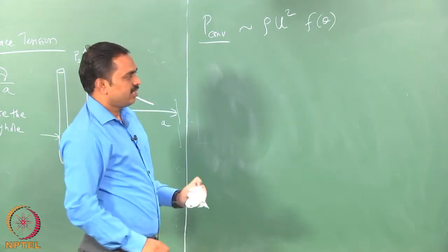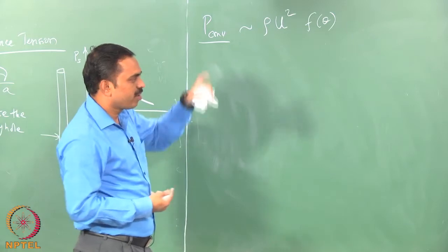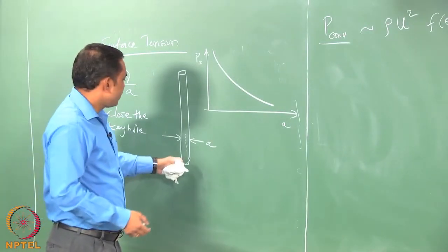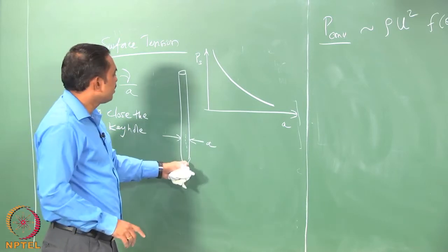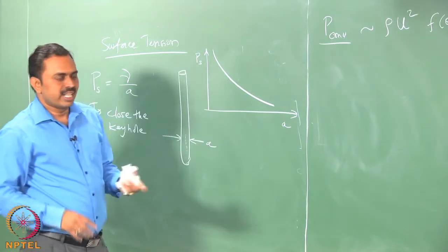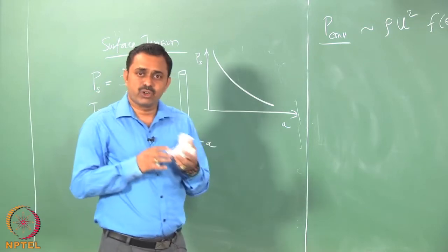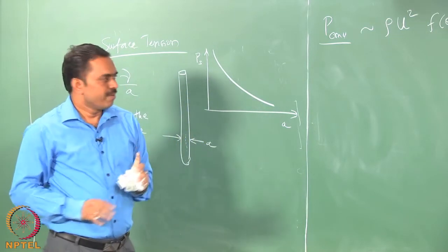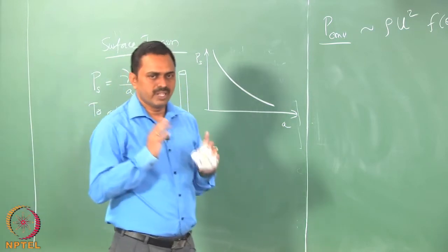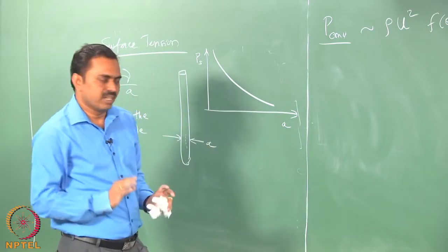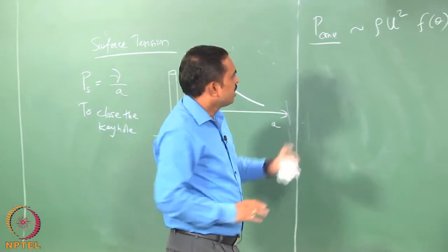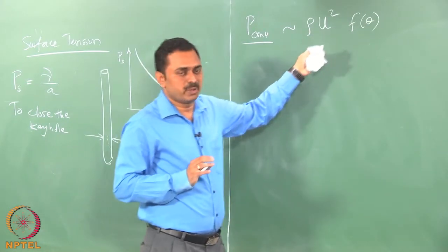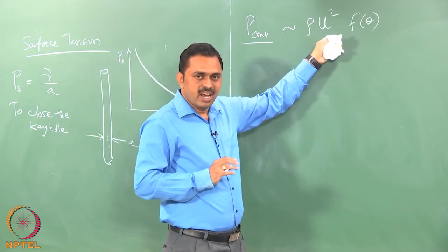Okay. And you can see also that the vapor column, if it is assumed to be almost cylindrical and the temperature is going to be same along the axis of the cylinder, then it implies that there are no strong temperature gradients along the vertical axis of the keyhole, which means that Marangoni convection is not going to be very strong. So, under that assumption that Marangoni convection is not strong, then the convection velocities are pretty weak, because other driving forces such as the buoyancy are not very strong.